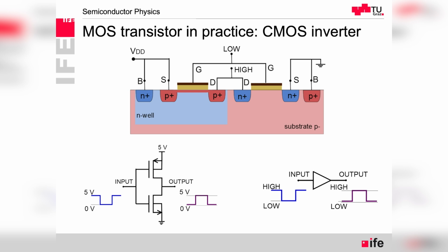And there are those two sets of parameters during the sample time. We would like this sampling to take as short a time as possible, so we care about a low time constant. That means the capacitance, maybe we can adapt and have a larger value of capacitance gives us better hold time properties.